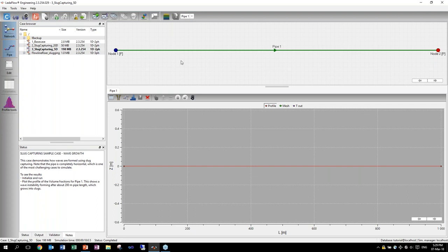With a larger mesh size, no, you would get different results with a larger mesh size and then going to a smaller mesh. The larger mesh size was really just to initialize the simulation to then rerun on a fine mesh. You could, or you probably will get different answers, not always, I guess, but I would think you would.